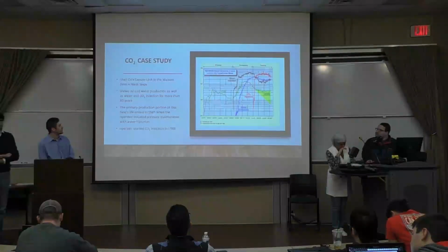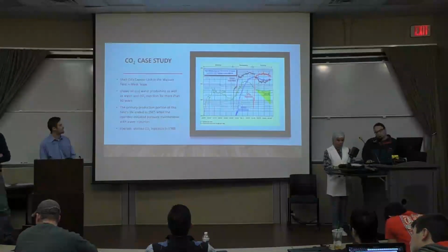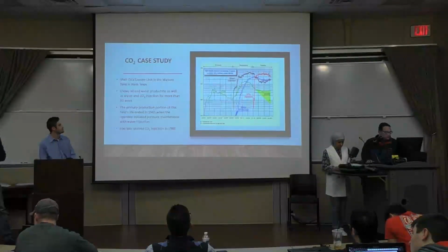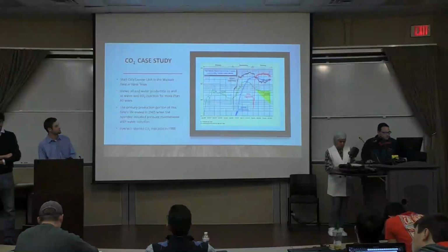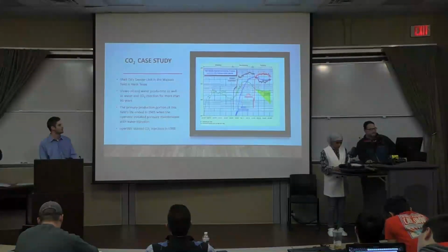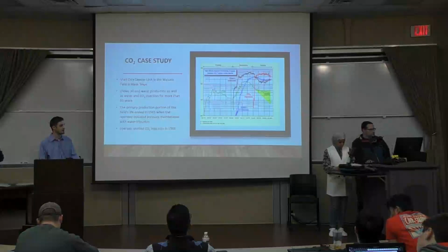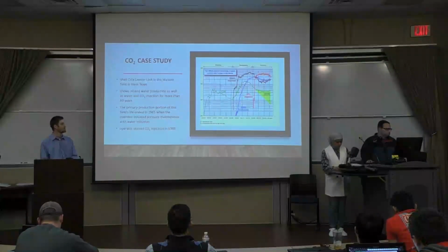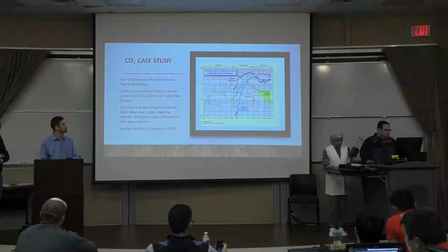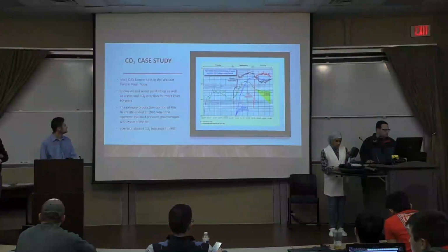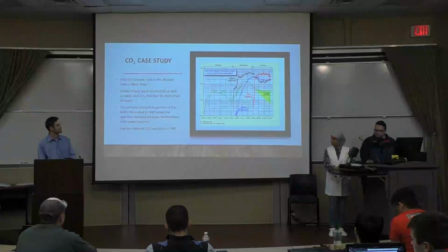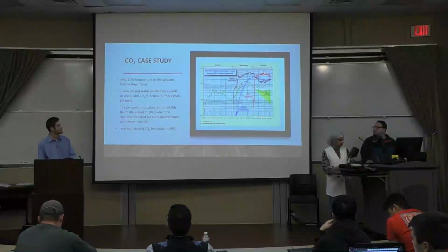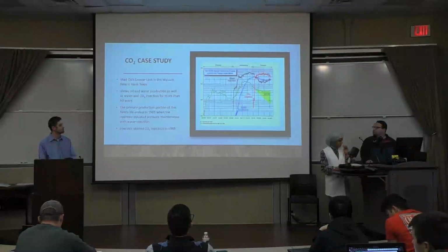You can see in the oil production curve, the slope in the secondary recovery seems to decline rapidly. If you follow that slope, that would have been the case if there was no CO2 injection. But with CO2 injection, it decreases the decline rate and gives you a higher incremental recovery. And this is just proof that it does work and it is very effective. In the past 15 years, it recovered a very good amount.